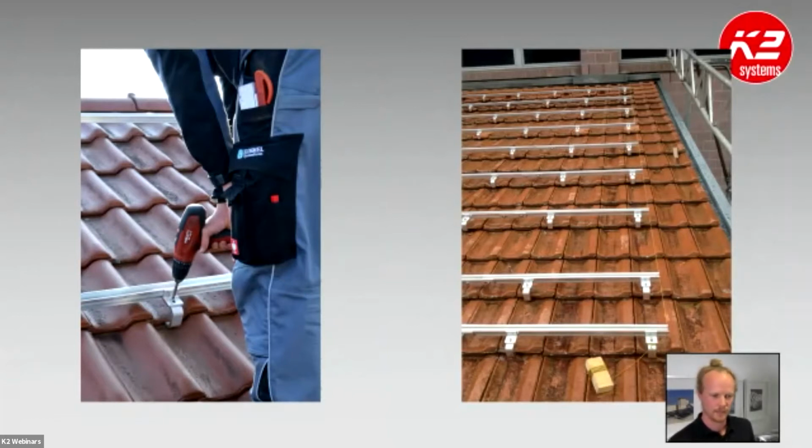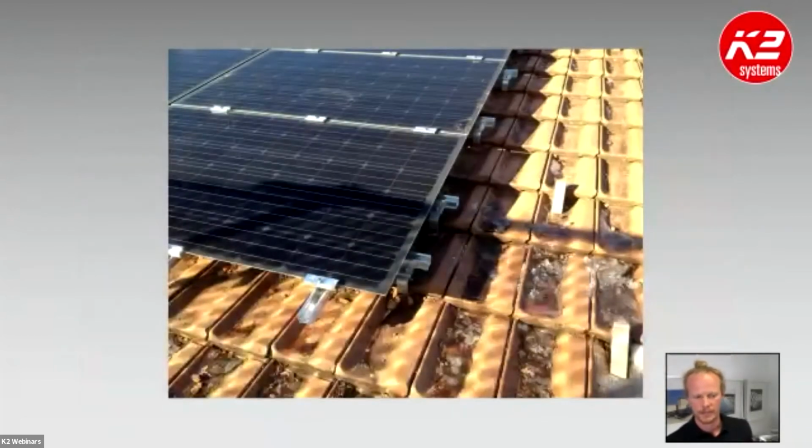So here we have the CrossHook 3, which I haven't introduced yet, but we will do so shortly. And you can see that the system is a single rail system because the fixation is being done from the top. If it was a solid rail system, the work would have to be done underneath. And then on the right, this is just all lined up, and then the final product. So this system is using cross bracing: one set of rails in parallel with the length of the module, and then one set of rails will run perpendicular.